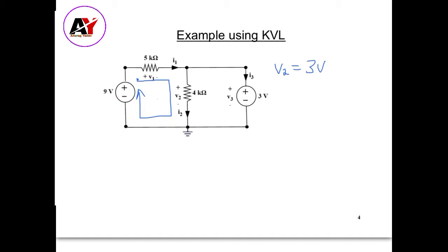My hint is that you should remain consistent in the direction that you are traveling around the loop as you write down the voltages, and write down the sign that you get to first in the equation.